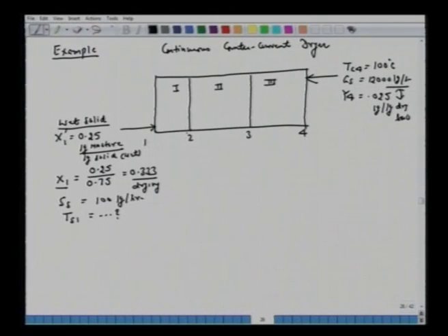And it says that this solid has to be dried to the temperature Ts4 of 60 degrees centigrade, and the moisture content x4 prime, wet basis, is 1%. So quickly we can calculate here x4 as 0.0101. All right. So the solid has to be dried from 0.333 to 0.0101. Flow rate of the solid is given, flow rate of air is given, moisture content Y4 is given here, and the temperature here is given. All right. So the gas which comes out has temperature Tg1, which is not known to us. It has humidity Y1, which is also not known to us. And for the gas or for the solid, we have to calculate whatever be the temperature or the moisture content in the air phase or in the solid phase.